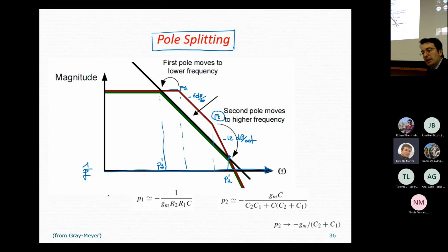So the slew rate, the output voltage derivative with respect to time, is given by the current which is driven to the loading capacitance divided by the value of the capacitance itself. Okay, so Vout is the voltage applied to this capacitor. So basically, we have this relationship.